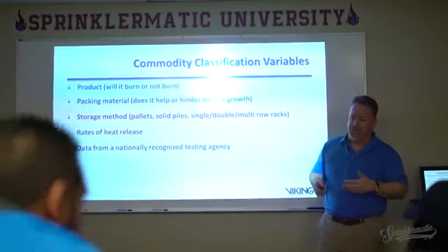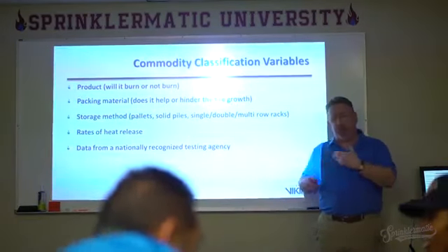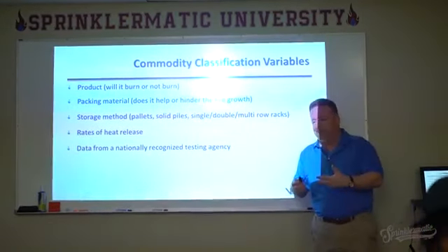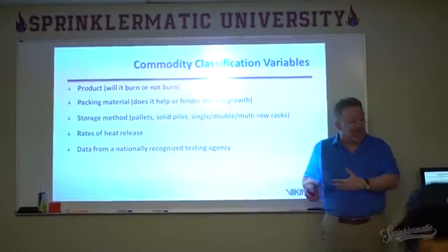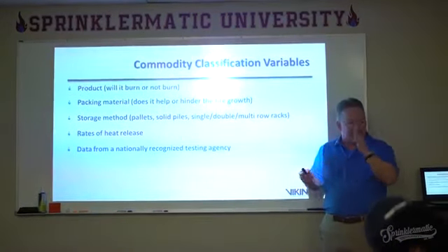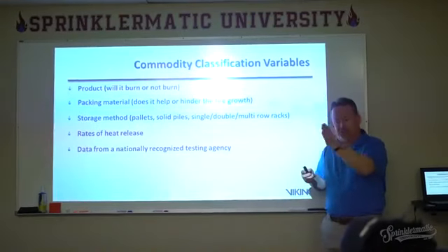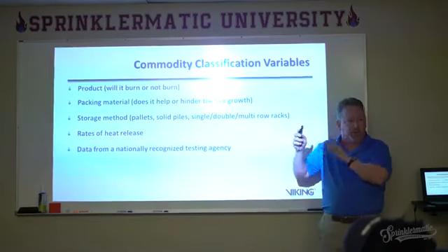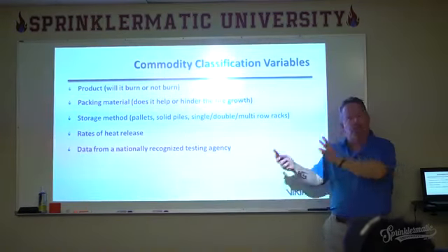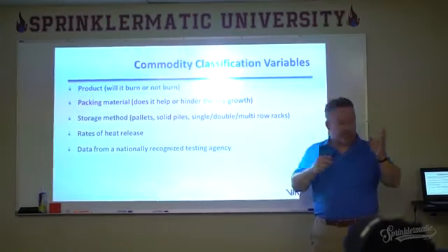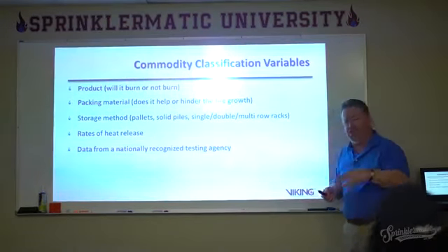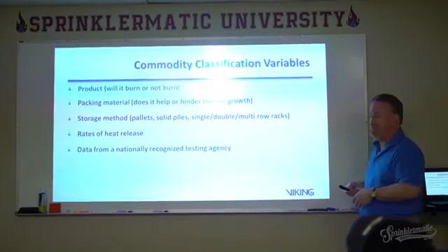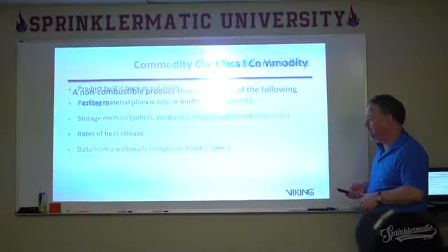So as we come up with all these commodities and start showing you examples of them in each of these classes, it doesn't mean that actual burning tests were done on each of those. We did a couple of burn tests back in the 70s and 80s, and then we started to compare each commodity to what was burned and say, all right, this will fall into this category. But as you'll see as you go through, the commodities in each of these families are pretty closely linked together.